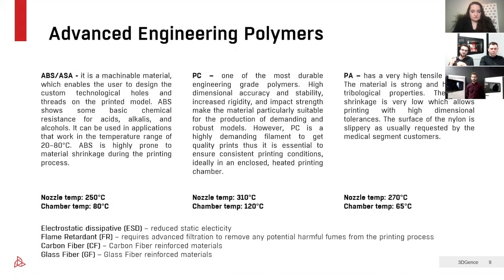And so to properly manufacture parts from polycarbonate, you could start at 117 degrees for some grades, all the way up to 140 degrees to match this requirement. And only then you can actually reap the full benefit of printing a polycarbonate part. This is actually what makes printing large pieces from polycarbonate possible. This is how it feeds into the design of the printer and the actual choices behind a 3D printer equipped to make good use of those materials.